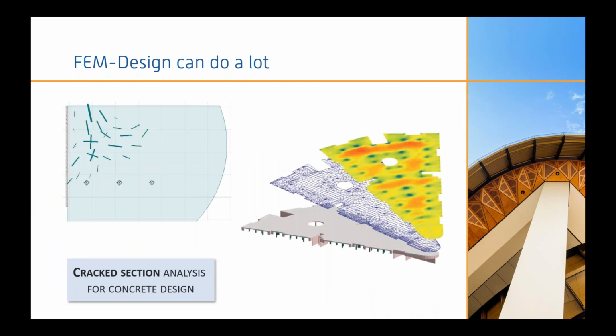One special feature that makes FEM-Design unique is the crack section analysis for concrete design. FEM-Design performs a nonlinear analysis where it takes into account the reinforcement in the concrete and takes into account the cracks. Once a crack appears, the stiffness in the concrete is reduced and the calculation is performed again in an iterative process.